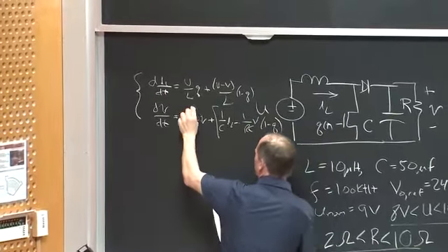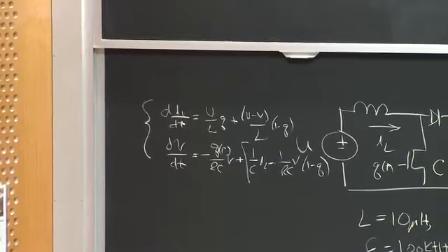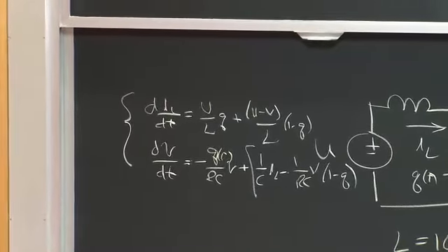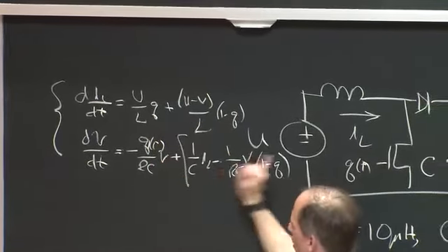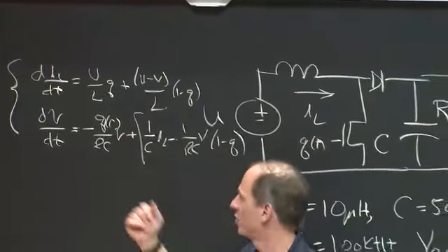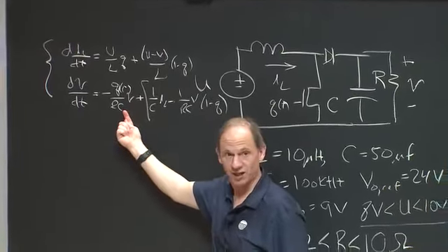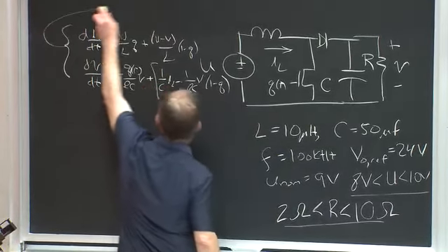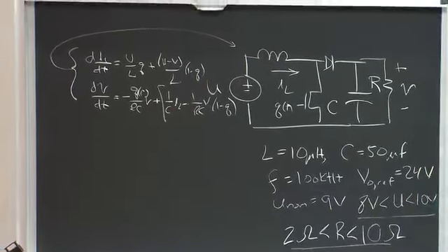And I should have said this is Q of T. Okay? So in this original model, all we've done is broken this down into 2 states and used my switching function to switch back and forth between the states. And if I knew initial values for IL and V and I knew Q of T, how it was modulating, basically, at least in continuous conduction mode, I could exactly simulate the actual behavior of that converter.